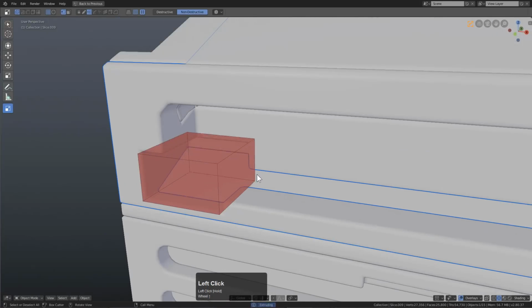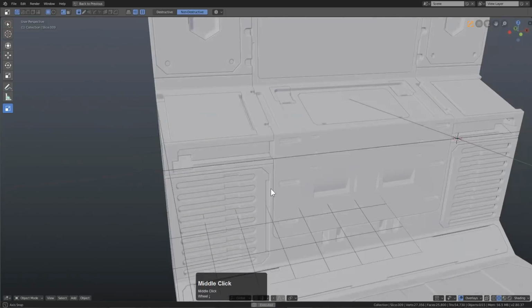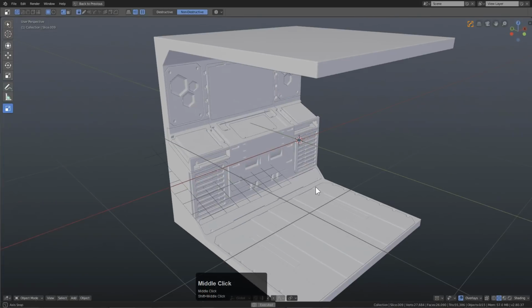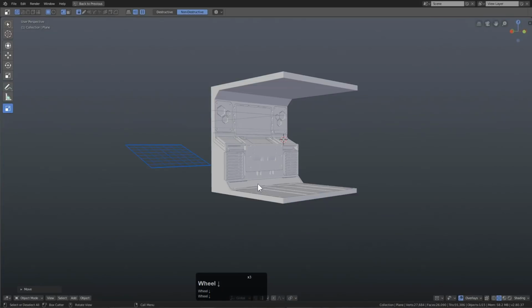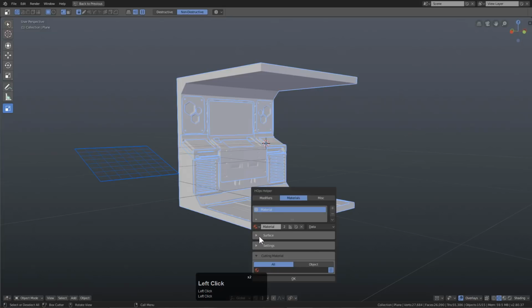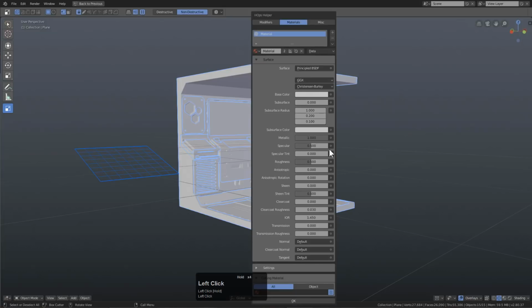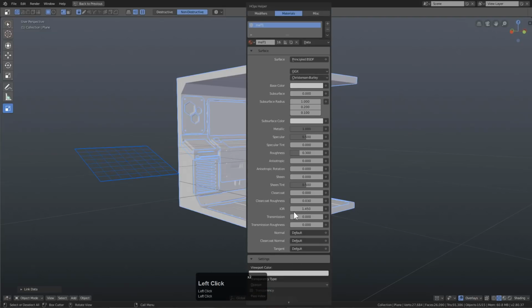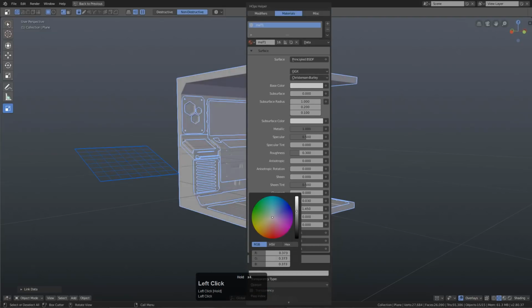So right here we have some problems. One way to fix it, cut it out. Super lazy, I know. Sorry, just had to. So right here we're just going to bring this piece in, press B, cut it in there, and while we're working on this, let's deal with some materials. I'm going to select everything, Control tilde, and we're just going to add a material. For this material, of course, we want it metallic. We want it to have a little bit of roughness. I've been in the 0.3 roughness area lately, and we'll just call this Mat 1. We'll press Control L and just share all those materials. And if we give it a viewport color that isn't white, you can see that all those materials got shared.